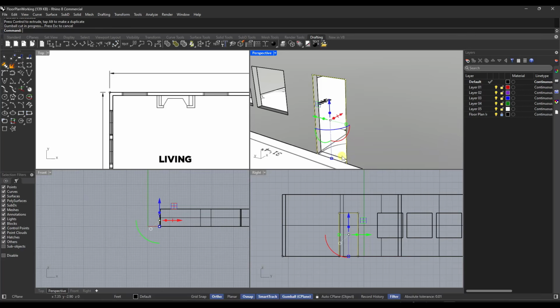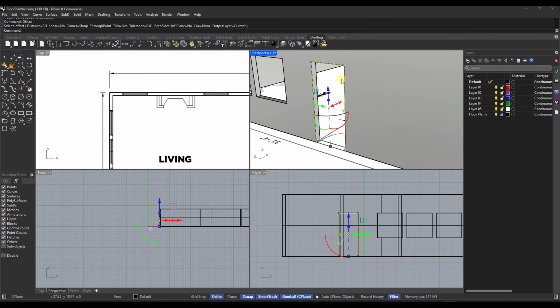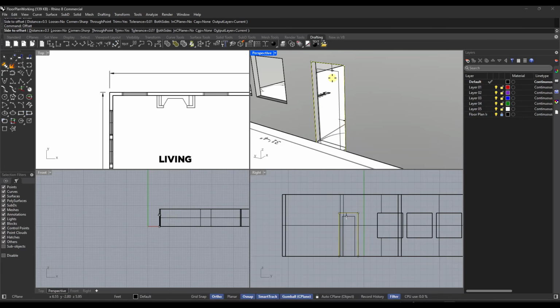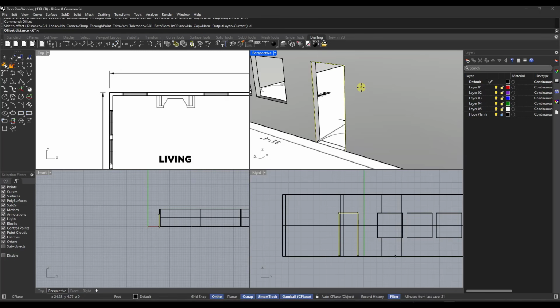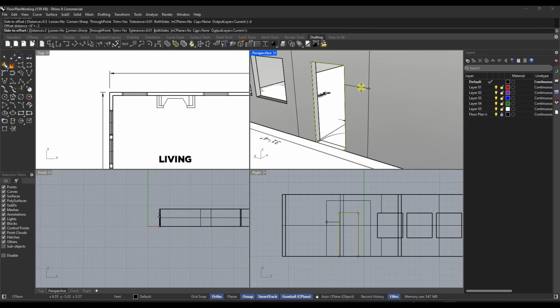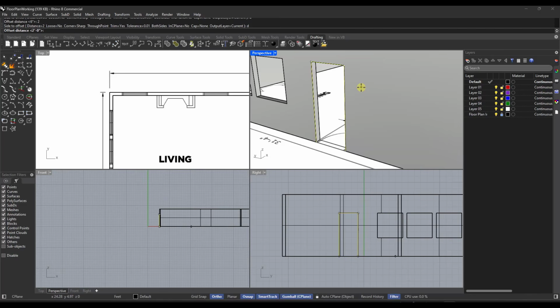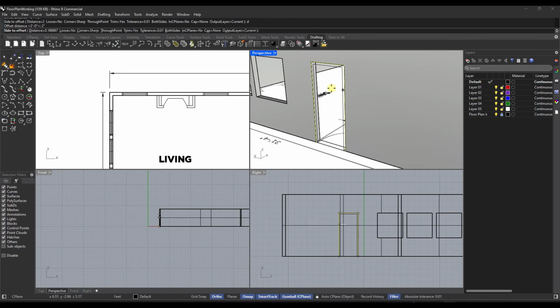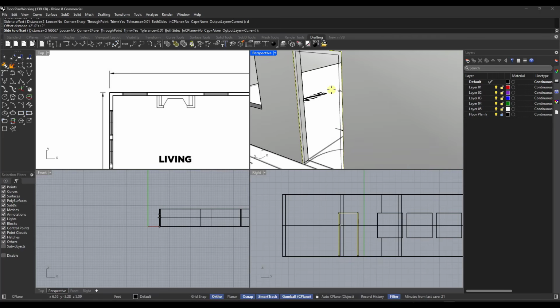And now what I want to do is inset all of those edges in order to create some thickness. So I'm going to use the offset function. I'm going to type in offset with these selected. Notice how I can use that to offset this out or in. One thing I want to do is type the D key and hit enter, and then type in an offset distance, which in this case I'm going to say is 2 inches, and this actually set it to 2 feet. So you want to make sure that you set this to 2 inches like this. Notice how you can move your mouse out or in order to do this. In this case, I want to move it in.